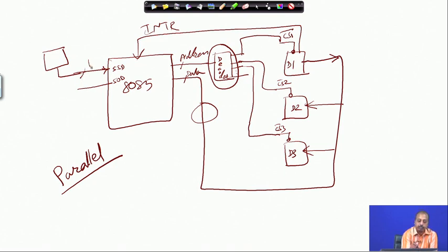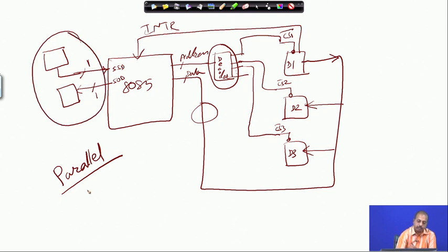So, this line width is 1 bit. Similarly, we can have the SOD, serial output data. If I want to output something to the device, again a 1 bit connection can be there. So, instead of parallel connection, this communication facility is the serial communication. The 8085 supports both types of communication, parallel communication and serial communication.